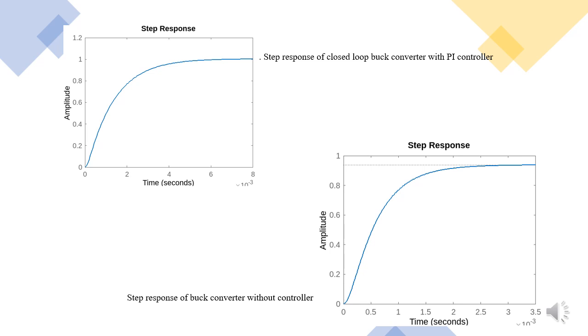This adjustment can be done iteratively, testing different values of Ki and observing the system's response. The process involves experimenting with different values of Kp and Ki, observing the system's behavior and fine-tuning the gains until the desired performance is achieved. It may require several iterations and adjustments to find the optimal values.